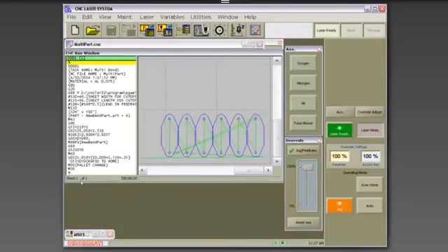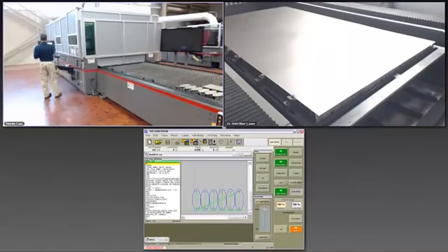Down here at the bottom, if you're doing multi-sheet nests, it'll tell you what sheet number you're on. And then right here, this is an estimation clock, so the operator would know how much time he has before this nest of parts is going to end, to get a raw material sheet on the other pallet, or to get parts off the current pallet. So I'm going to go ahead and run this. A lot of these programs, I purposely slowed the feed rate down so that you could get an idea of the programming techniques that Scott spoke about.